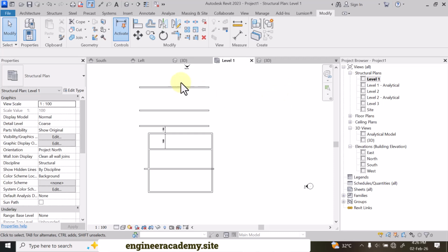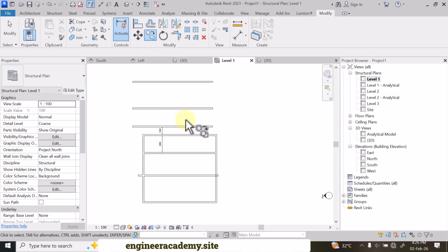The second way you can use copy in Revit Structure is you can pick copy to first. Then when you pick copy to, you can now select the object. If there are many objects that you want to select, maybe many structural walls or beams, you hold Control and select as many as you want to copy.